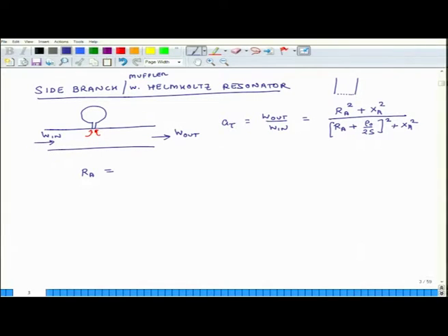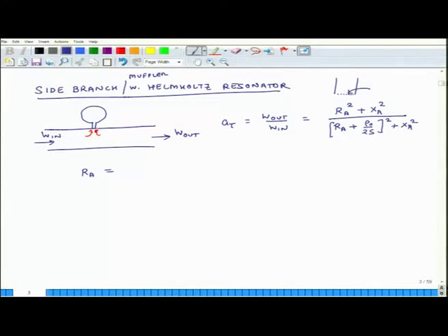So, as sound goes in, it has to pass through this crisscross pattern of wire mesh, and this acts as an acoustic resistor, because it obstructs the flow of sound into the pipe. Now, I can have one situation where I do not have this mesh, I can have another situation where I have this mesh. So, let us say when there is no mesh,